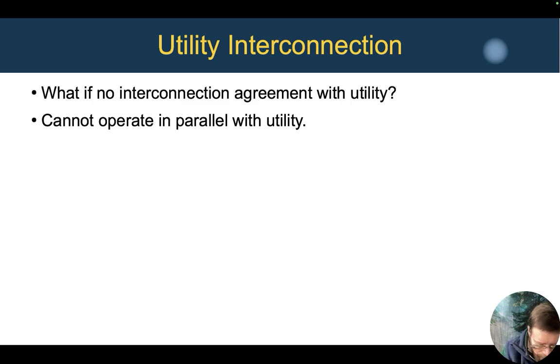The new smart meters can often detect if there's solar operating in parallel, because as loads go up and down in the house, say a really large load suddenly turns off, the solar may inadvertently export power to the grid, even if it's only for a second or two, for 100 watts or less.